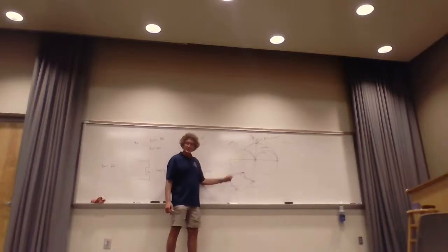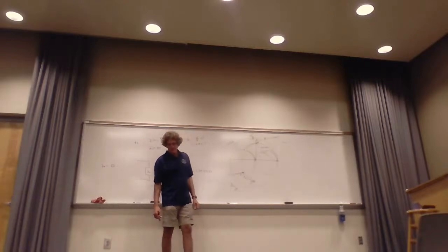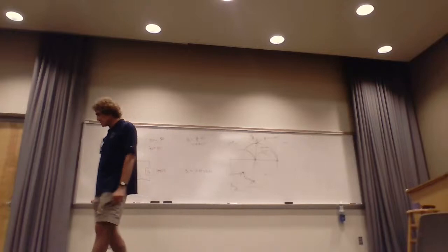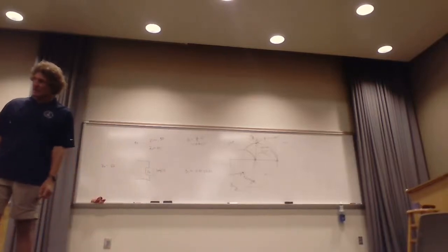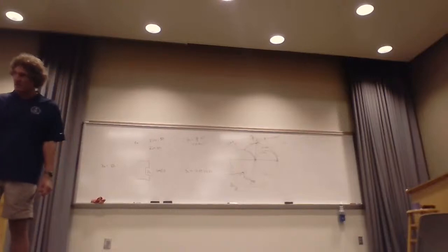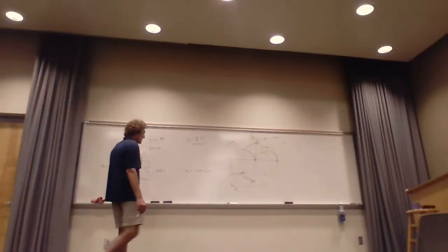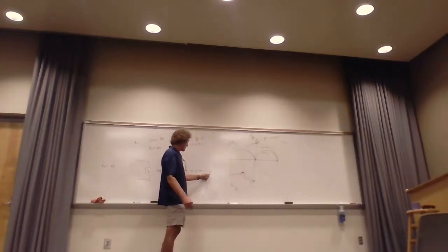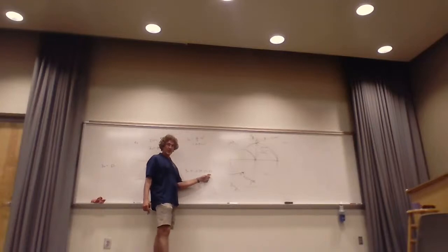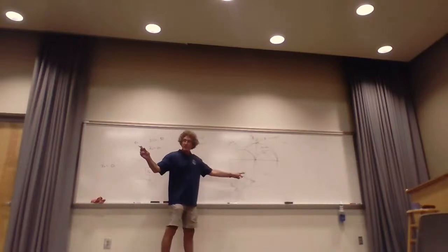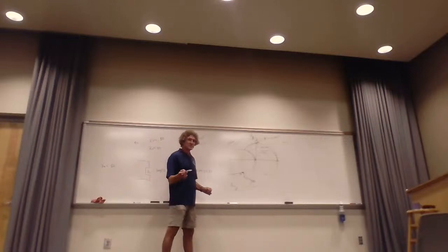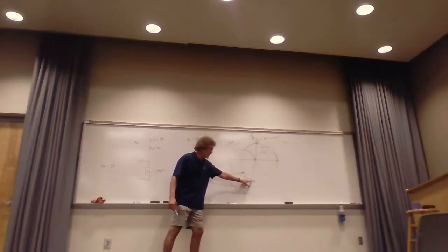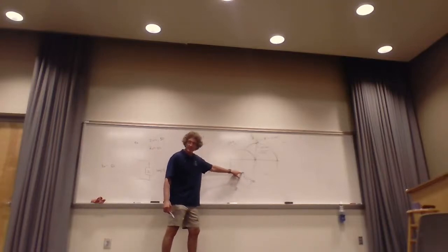Take a look at this point right here. It just has a B. What does he add to it? Well, here's what happens. That's 0.2. It's going to move here. So whatever this is, you got to take a look at the J value here is 0.86, right? What we have to do is add to that a J value to get on the rim of this thing. If you had a rotated Smith chart, you could look at 0.34, the real part, and you could see where it intersects that rotated circle.